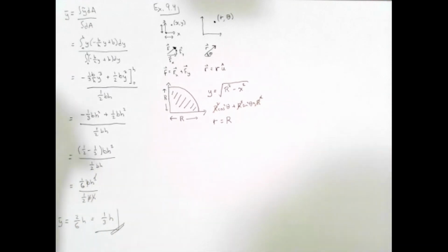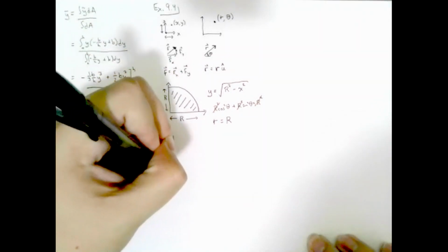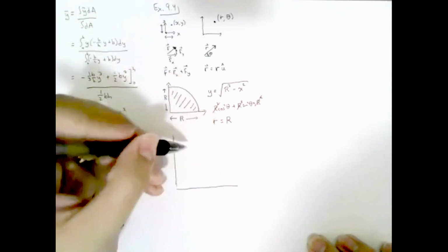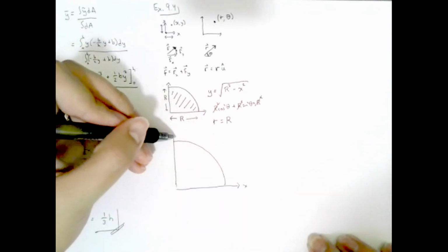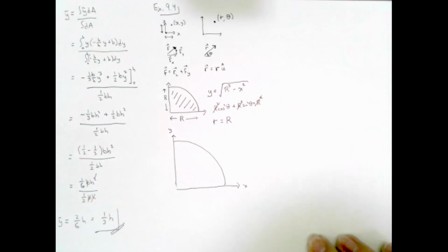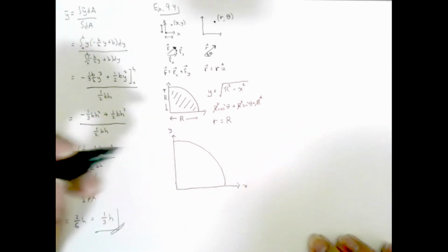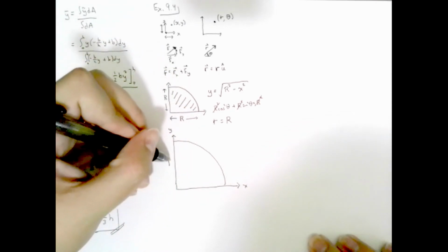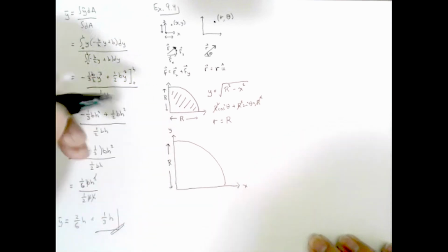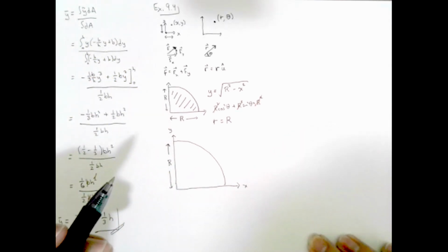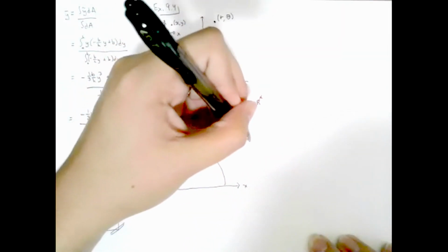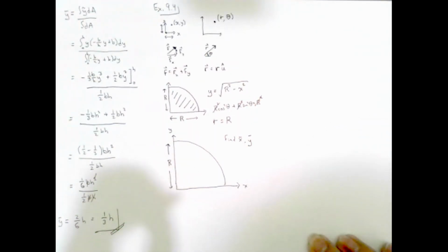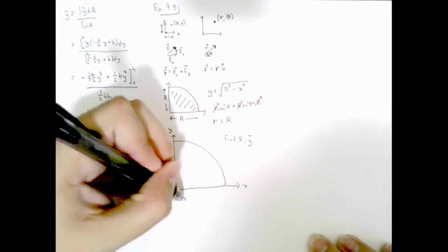And I will show you how they make our lives easier by solving an example that requires us to use polar coordinates, okay? So in this example, let's find the centroid of this quarter circle, okay? I'm only drawing my X and Y axes as reference because since we're gonna be using these equations for centroid, we're gonna have to switch between the two. And let's say that this circle has a radius of capital R. That means that the distance from the origin to any point in this line is gonna be capital R. I wanna find my X coordinate of the centroid and my Y coordinate of the centroid. However, because I'm dealing with a circle, I would like to use polar coordinates.